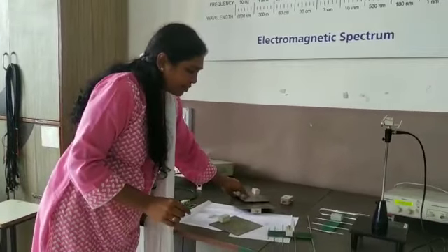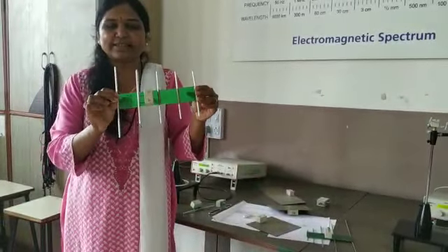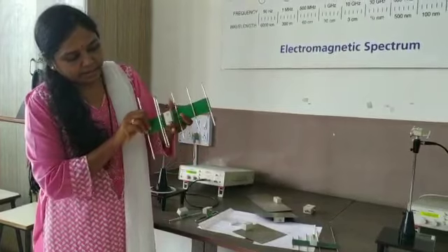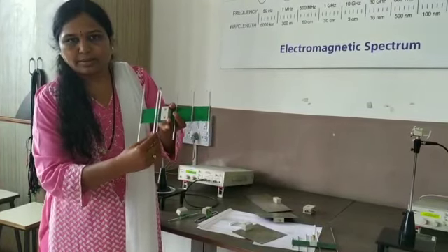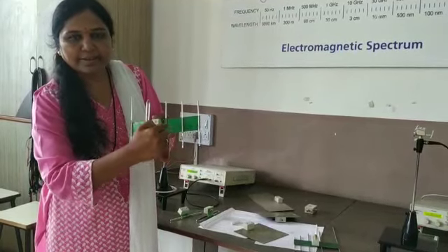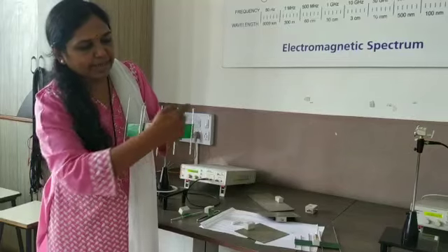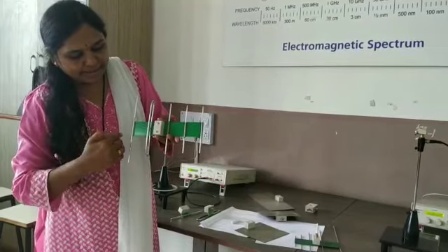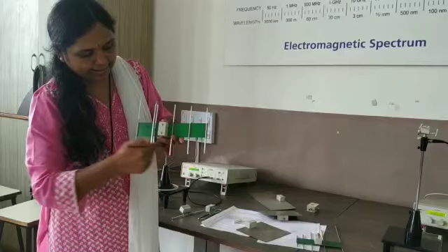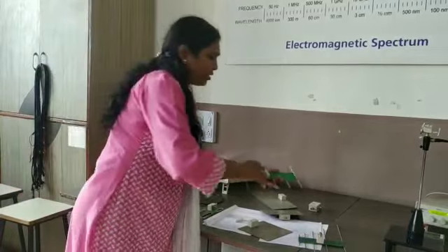Then there are some array antennas also. You might have seen this antenna. This is nothing but the Yagi-Uda antenna, Yagi-Uda array antenna. Here this element is called the feed element, and this is nothing but the reflector, and these elements are nothing but the directors. Actually, if the antenna is kept like this, then maximum radiation would be in this direction. The reflector reflects the electromagnetic energy in this direction, and the directors are used to direct the electromagnetic energy in this direction. Therefore, we can use this Yagi-Uda antenna to improve the directive gain of the antenna.